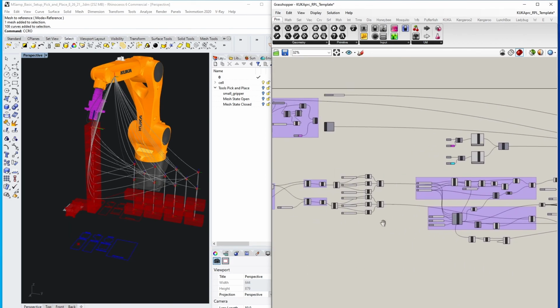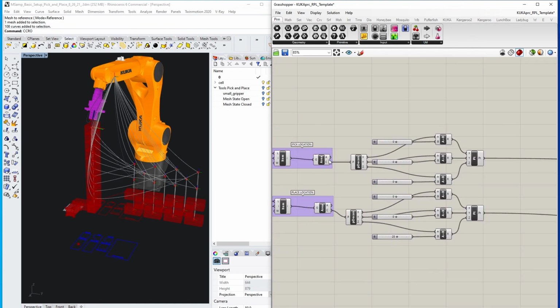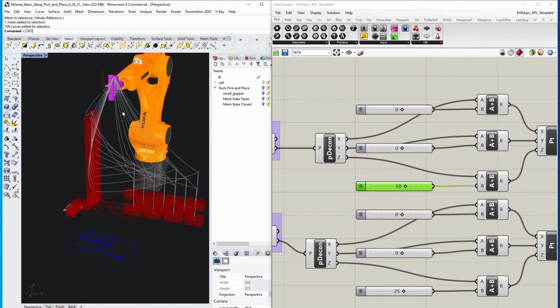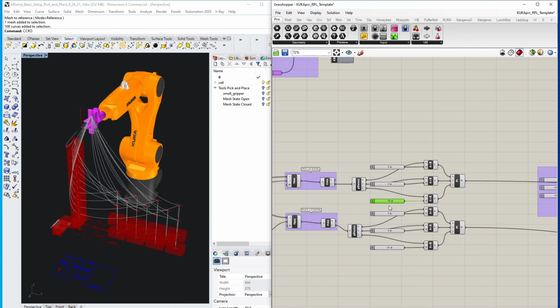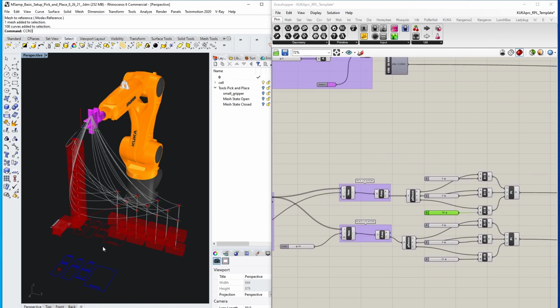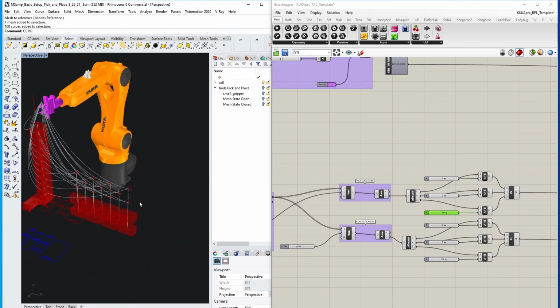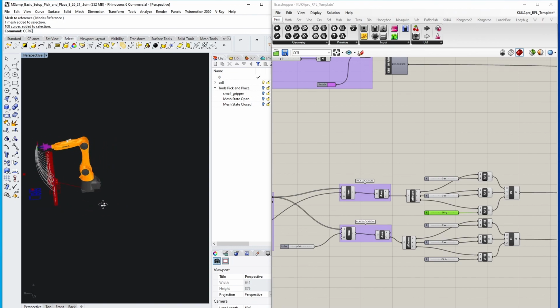One thing I also suggest is that you increase your pick location by at least 50 millimeters before running your file. So by increasing your pick location in the Z direction, you can guarantee your file doesn't have any errors when you're running it on the machine. Make sure that you don't have any objects in place, but that you use this time when the Z height is actually higher in order to accurately position your placement map. And from there, you can actually run the file and make sure that it works.